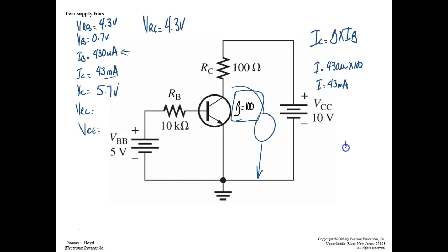If I would have drawn this circuit like this, and put a rheostat right there, and said I'm putting 10 volts right there, and this guy is dropping 4.3 volts, how much voltage drops across the rheostat? Everybody would have said 5.7 volts. But for some reason, you can't picture the transistor as being a rheostat. That's all it is. It's just a rheostat that we're controlling electronically. So with this base current I've adjusted this rheostat to drop 5.7 volts. But we didn't know that.